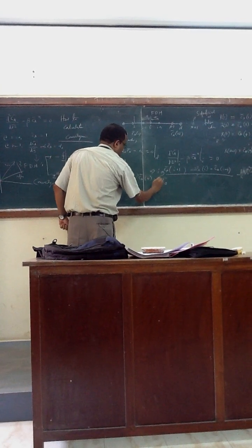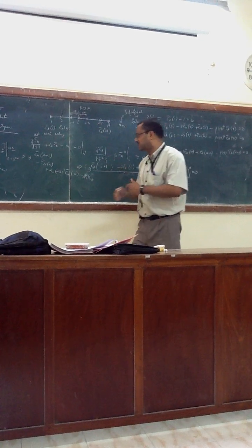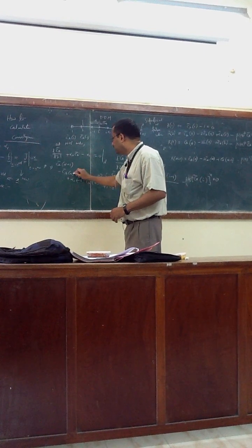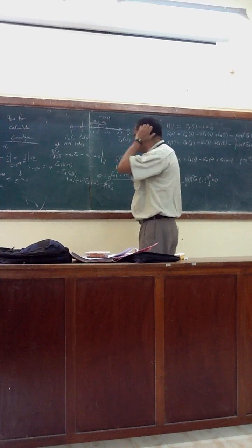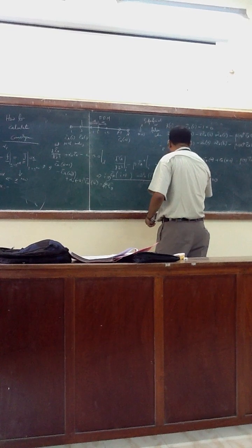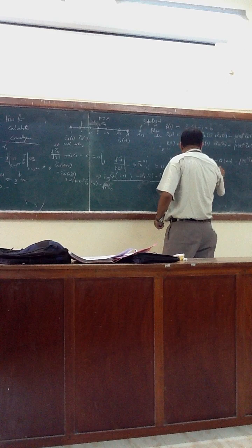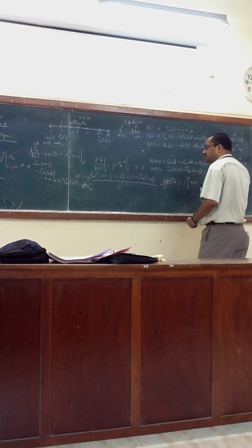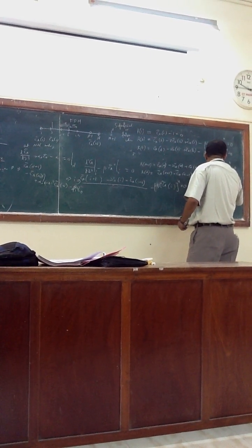I don't remember the formula. 2 delta z, right? yi plus 1 minus yi minus 1 by 2 delta z. What is that? CA bar n minus 1. Okay? So your Rn will be CA bar n plus 1 minus CA bar n minus 1 plus alpha 0 2 delta z CA bar n minus alpha 1 2 delta z equals to 0.